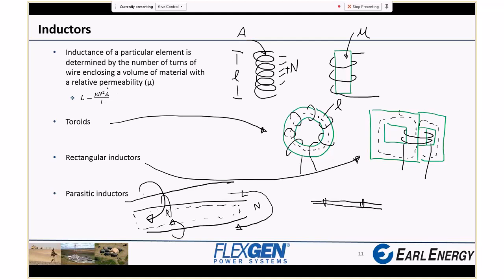Or if you were dealing with, it's going to be very rare where you're dealing with air core inductors and you're playing with area enclosed by the winding. So that's important. Just this n squared. If you want to double the inductance, you put on 40% more turns. It's the square root of 2, 1.414. That's probably the important thing to take away from this slide.